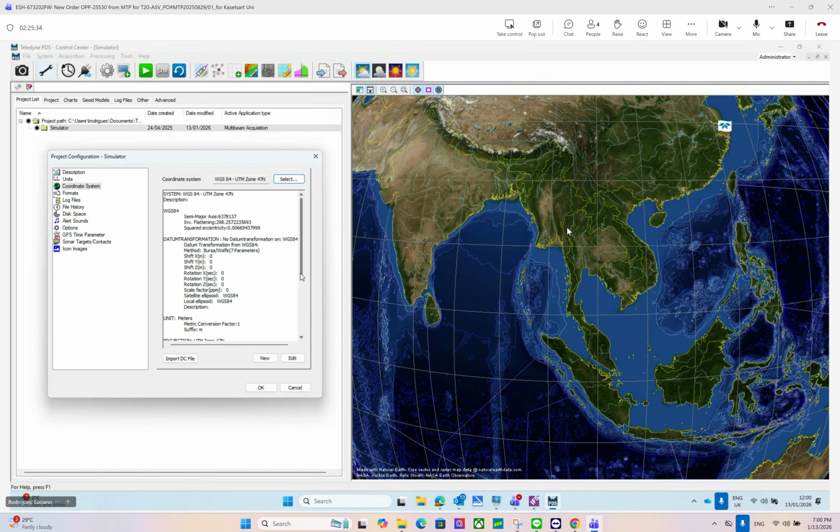And the only way to get heights, in other words, where you expect a negative height for the water, maybe 10, 20, 50, whatever meters, you're not going to get that. You're probably going to get something which is, and I don't know what the ellipsoidal separation is in Thailand, but I know here in Scotland it is about 45 meters. So I generally tend to get something like 45, 47 meters, and it's a positive number.